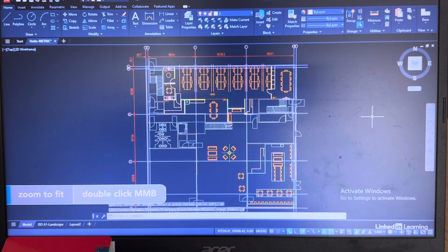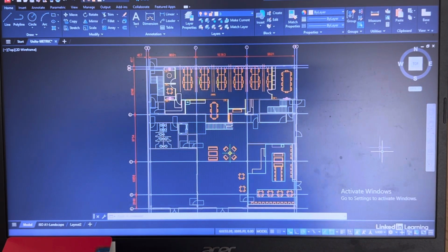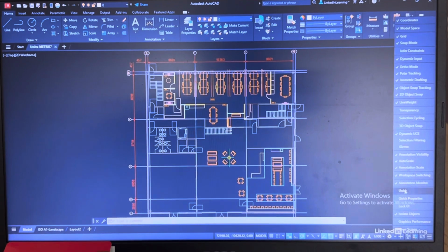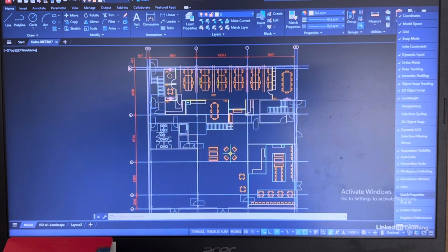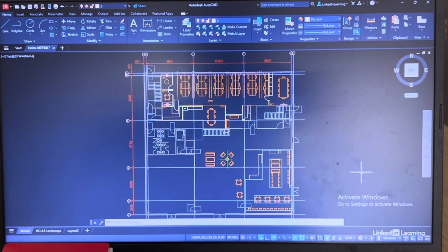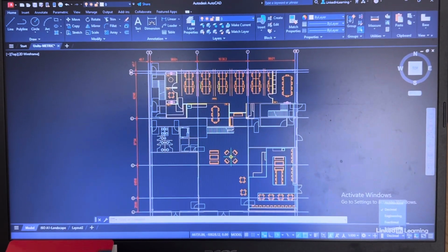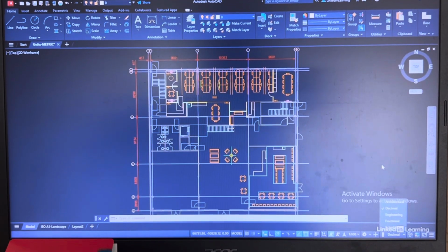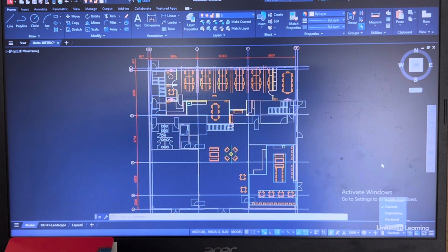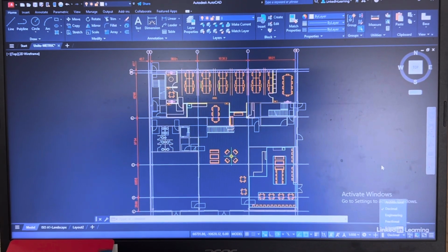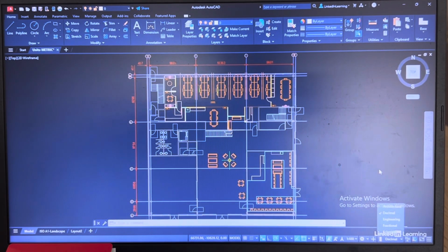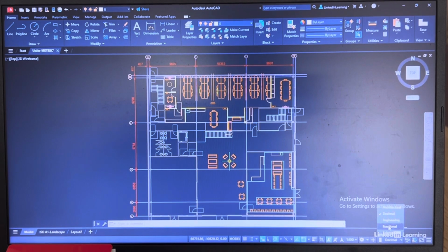Now, talking of customization and the status bar down here bottom right, if you click on those little three lines again on the customization, look there, can you see units? Switch that on and then click on the little three lines to lose the customization menu again, because that will tell you what your unit settings are. You're using decimal. Excellent. So if you're using decimal, that gives you an idea normally of what kind of units you're working in. Now obviously you can display imperial measurement in decimal. You can have 0.5 feet, for example, or 0.2 inches. But more often than not, if you're working in feet and inches, it'll be something like architectural, engineering, or fractional.